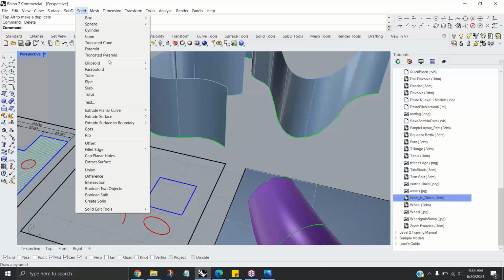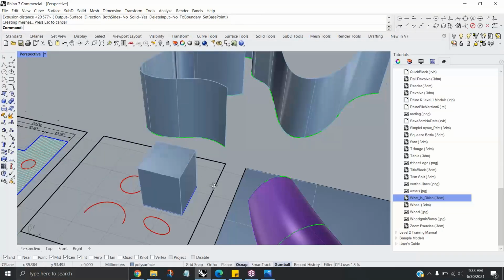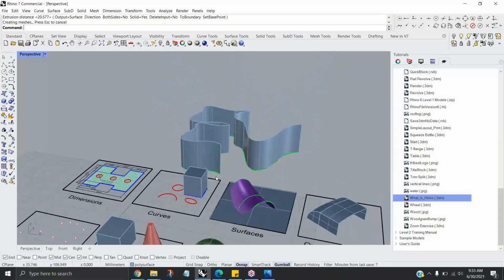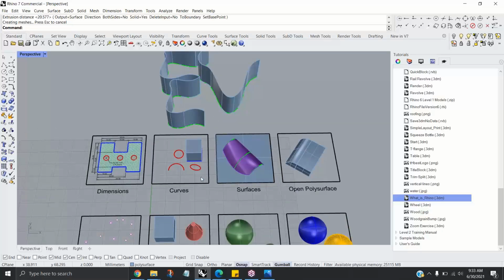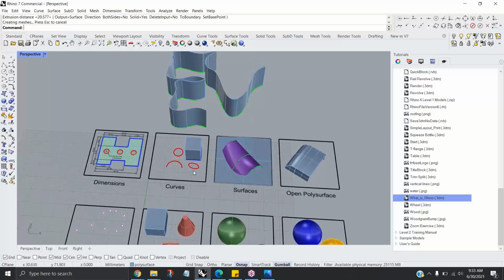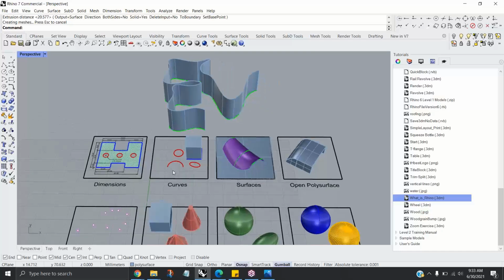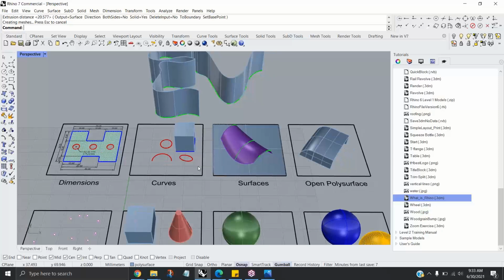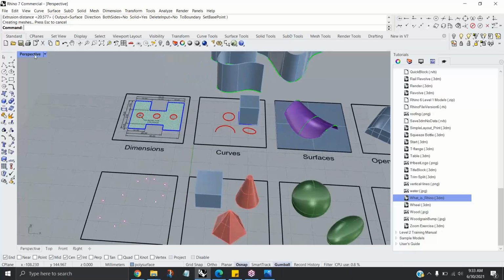However, if I do solid extrude planar curve straight, this one by default will have a cap on it. Okay, so this is how we get from curve geometry to 3D geometry, is by using the curves that we create as input for surfaces. And the modeling aids of object snaps and the gumball are going to be really important to our project.